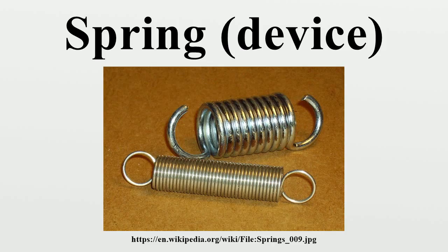When coiled it adopts a flat cross-section, but when unrolled it returns to its former curve, thus producing a constant force throughout the displacement and negating any tendency to rewind. The most common application is the retracting steel tape rule. Progressive rate coil springs, a coil spring with a variable rate, usually achieved by having unequal pitch so that as the spring is compressed one or more coils rests against its neighbor. Rubber band, a tension spring where energy is stored by stretching the material.